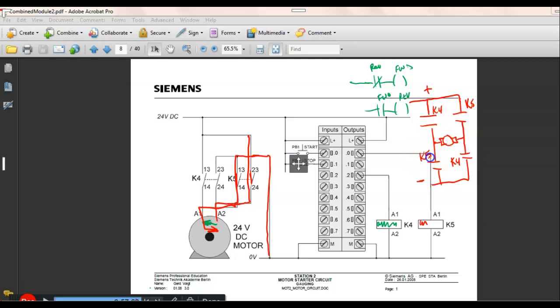Now this is the reverser that we have. The electrical interlocks are not in the relay coil, so the electrical interlock should be inside the, but it does have this. So it's got a mechanical interlock, so I can't force them in at the same time. You know, I showed y'all last class how we can actually move this carriage back and forth by hitting the relays. But I could not do what? I couldn't push them both in at the same time. If I ever let these two relays come in at the same time, then that would be a problem.